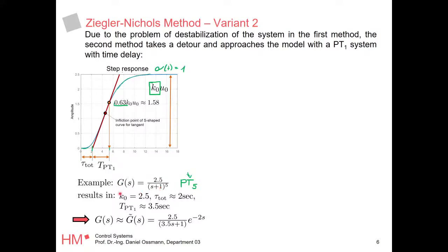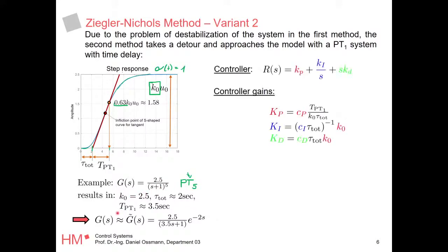What's important here are mainly these 3 parameters, because based on these 3 parameters, you first decide which controller you want to take. You want to go for P, PI, PD, whatever. And then you calculate your controller gains. And actually, these should be small caps here. I forgot to replace it. So this is a small Kp, small Ki.